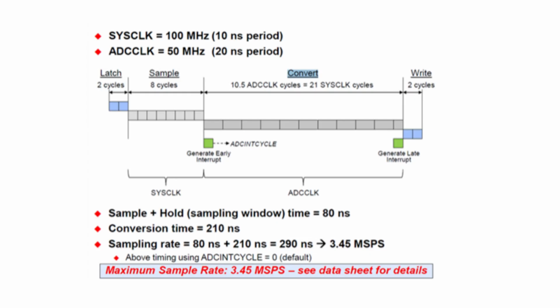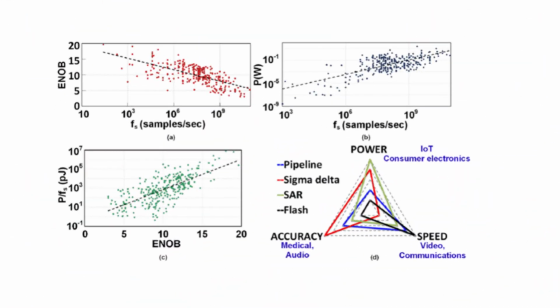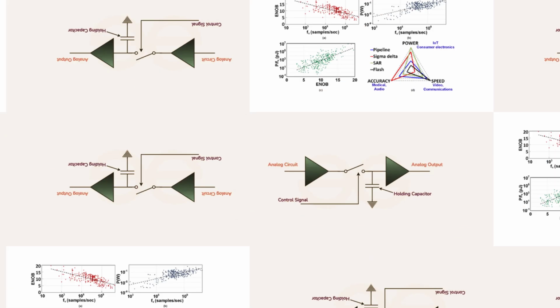Short versus long? Okay, a short sampling time, maybe just 3 or 15 ADC clock cycles, allows for the fastest possible conversions, maximum throughput. But it puts a big demand on your sensor circuit. Your sensor needs to have a very low output impedance, meaning it can supply current quickly enough to charge that tiny sample and hold capacitor in that very short time.